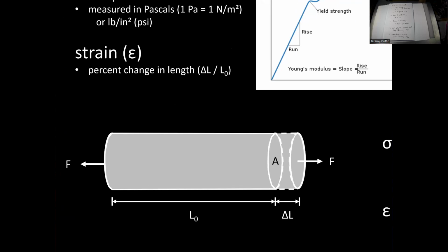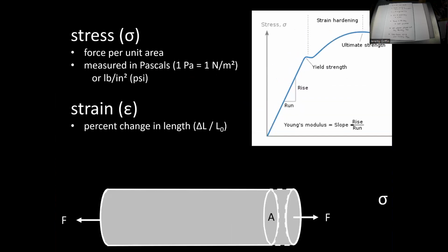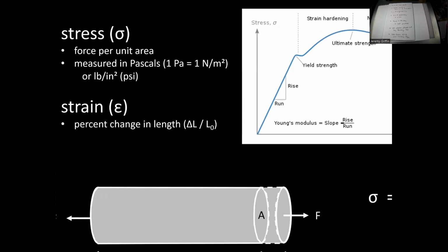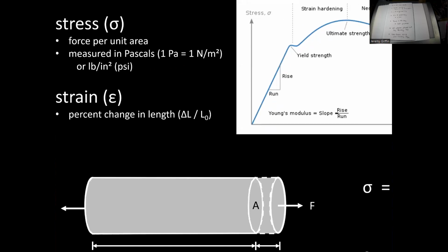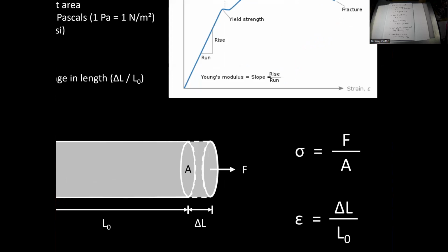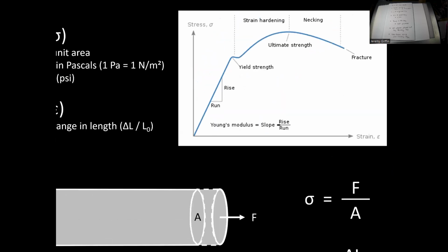Now for concrete, just reverse the direction of the forces to make it compression, right? You're going to push on concrete. Push, push, push. And when you apply a stress, force divided by cross-sectional area, that's what stress is. It could be in pascals, megapascals, PSI. A strain is going to result. Strain is just a percent elongation. So how much does it change its shape? What percentage does it change its shape? That's a change in length divided by original length. This divided by this, right? That will be the strain. And that stress-strain relationship is linear as long as you are within the elastic zone.